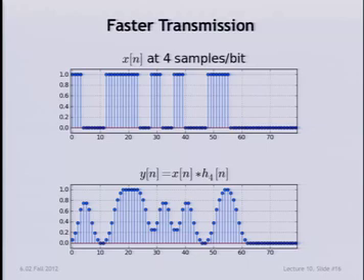Well, now you again are going to superpose the step responses. But what's happening now is you've gotten so ambitious with how fast you want to get the bits across that you're not giving the step response time to settle. So over here, yes, there's time. The step response went up and settled because you had 3 1s in a row over there. But now you're going down to 0 for one time instant, and then jumping right back again. Well, here's the flipped over step response, and it doesn't have time to make it all the way down.